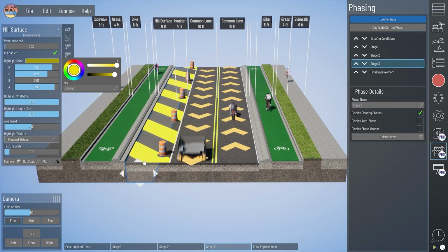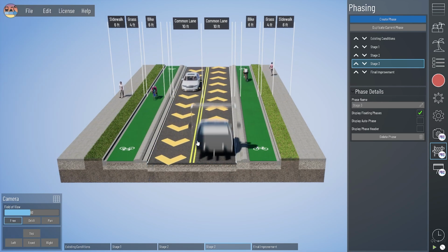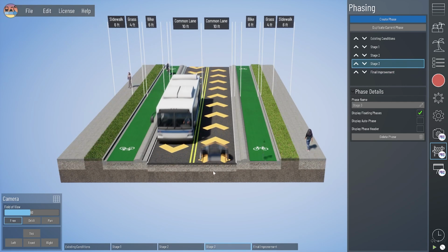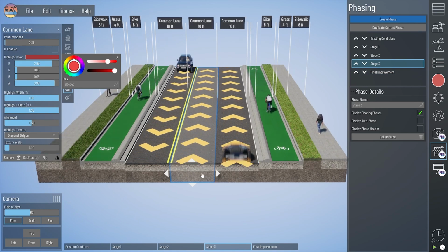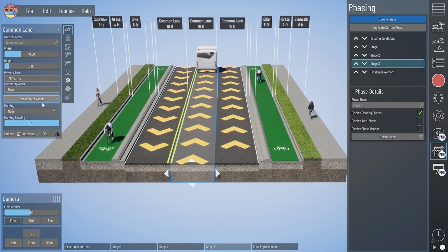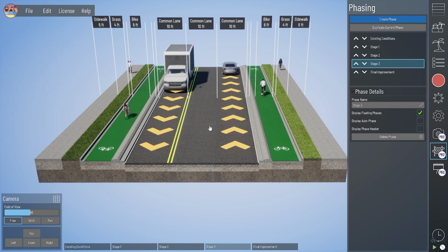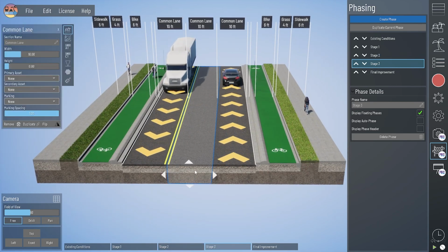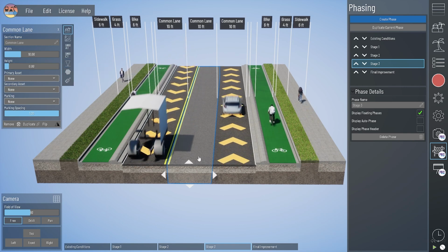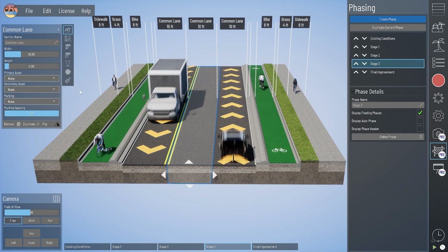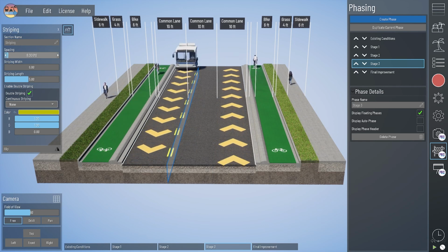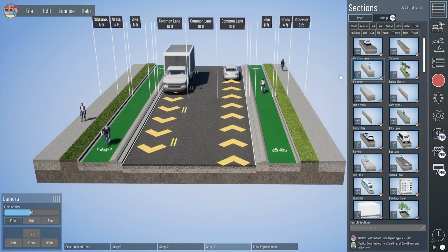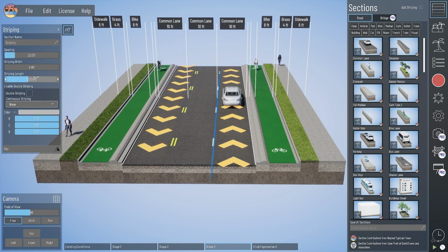Then instead of a mill surface and a shoulder, we've got our two 10-foot common lanes that'll match the final condition. And then all we need is another common lane in the middle there without traffic. And then I see this a lot during staging and maintenance of traffic where those stripes may not be fully striped down the road. So let's show more of a temporary stripe. We'll put some spacing on those double yellows just to represent some interim striping, possibly tape in the field.